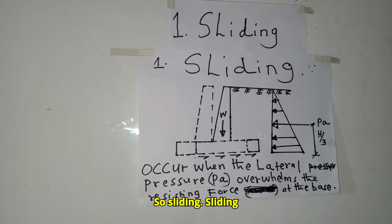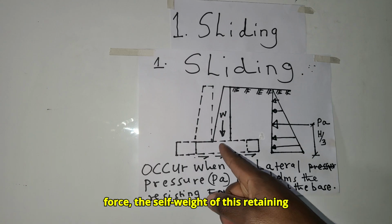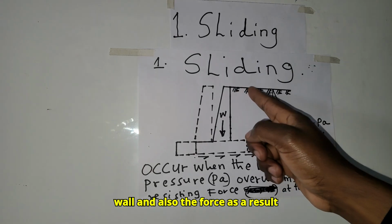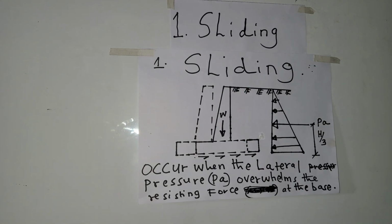Sliding occurs when the lateral pressure, which is PA, overwhelms the resisting force at the base. The resisting force is the summation of the vertical forces. Here, it will be the self weight of this retaining wall, and also the force as a result of the backfill.